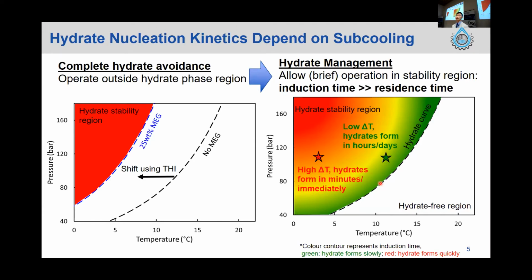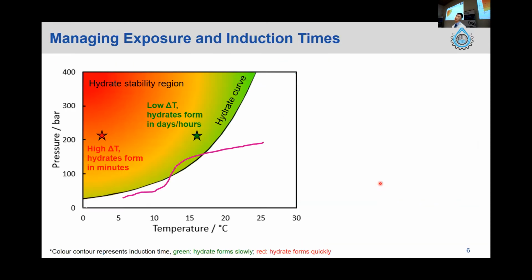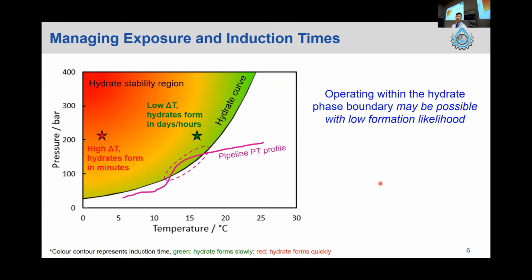So if that's the case, then you need to think about your residence time. How long do the fluids actually sit within the hydrate stability region? Is it a matter of minutes, hours, or days, right? That is the question we need to ask ourselves. So we can generate experiments in the laboratory and compare those induction times with your residence time.